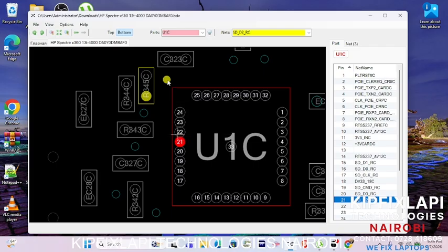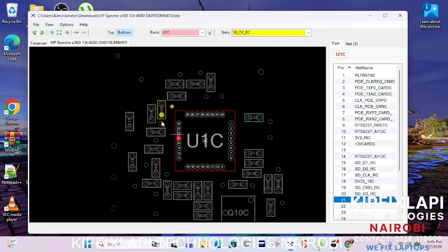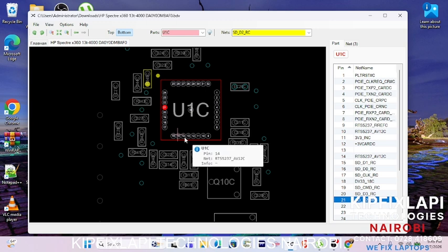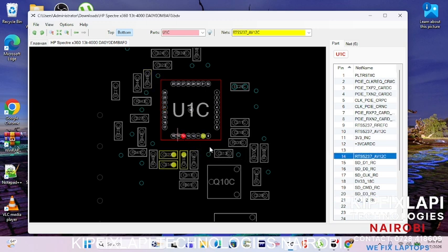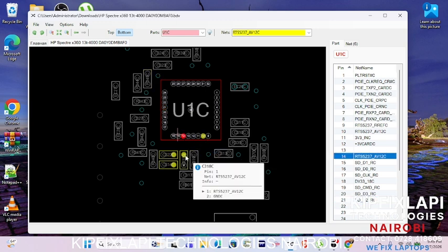You can also connect it to here. Even though you might not know what this dot does, you know it should connect there. So that is one of the importance of the Boardview files. You will be able to see this pin number 14 was supposed to connect to pin number 1 of this capacitor, because this is a capacitor. When you bring your cursor near to that, you will see the popping up details about that component. I hope you can see on my screen.